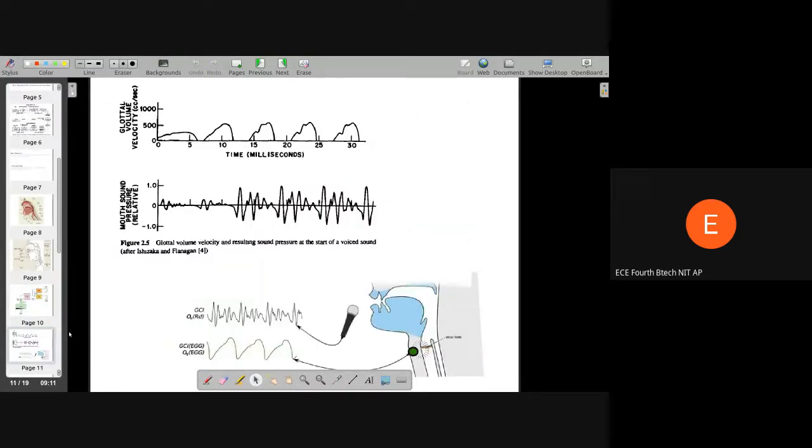The next main thing we talked about was glottal vibration. What is an EGG signal? Voiced speech and unvoiced speech. In speech, generally voiced speech or vowel-like sounds have a kind of periodic nature. Not exactly periodic like a sine wave, but you can see there is some periodicity there. In our signal processing terms, we call that the fundamental period of speech.